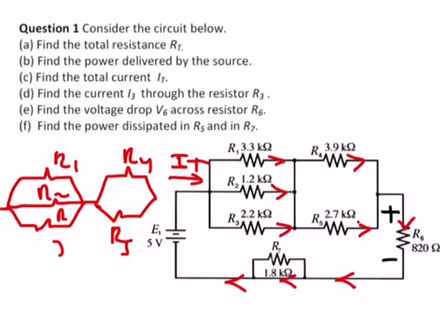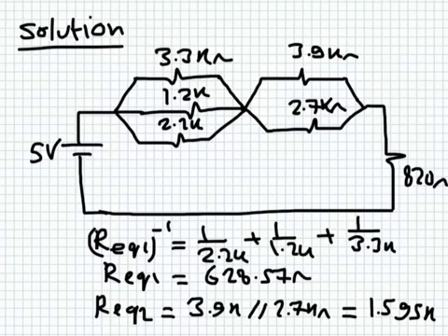Everything is exactly the same. So first, let's redraw the circuit after we get rid of R7, because R7 is shorted out. And after that we'll make these three points just one node, and then we'll start to analyze the circuit. So this is how the circuit now looks. It's obvious that this resistance and this resistance and this resistance are in parallel.